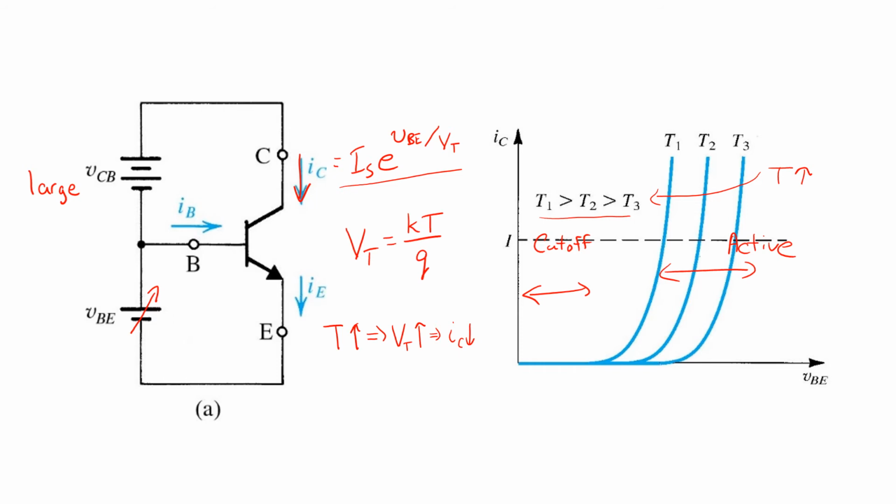This is a key point because if you imagine the bias voltage being kept constant, I'm not even able to draw a straight line there and illustrate the point because the voltage-current relationships are so steep there. But imagine keeping the bias voltages roughly constant, and as the circuit is activated, some current starts to flow, and that current flowing across a voltage drop through the BJT will result in some heat dissipation.